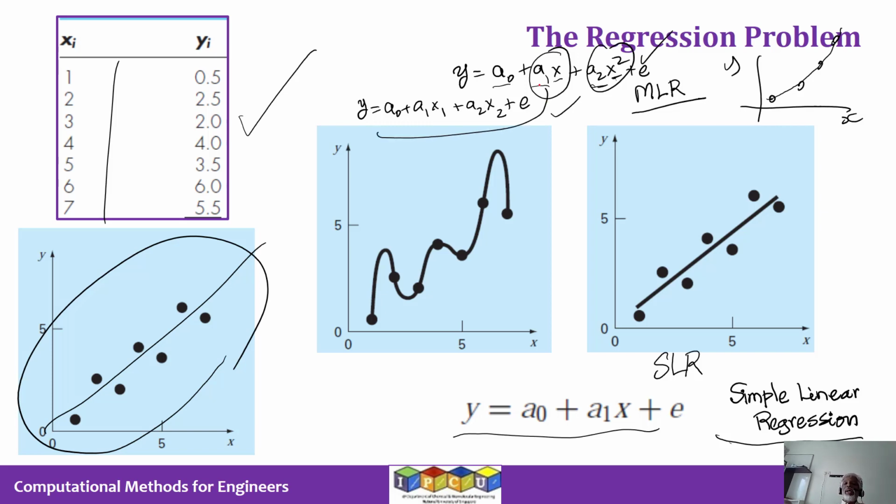Sometimes this form may arise very naturally. For example, if you take a distillation column, which has got a feed, a product stream, a vapor stream, and a liquid product stream. Now, what can happen is if I'm trying to get a model for the composition in the distillate stream, that composition may depend on the feed composition. It may depend on the amount of steam that I put in the reboiler. It may depend on certain other characteristics of the system. For example, you can see that the temperature of the top tray predicts this overhead composition very well.